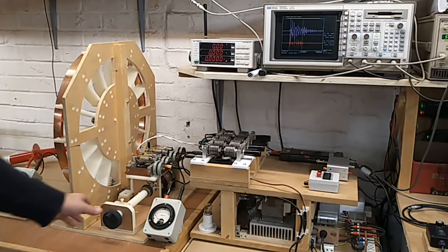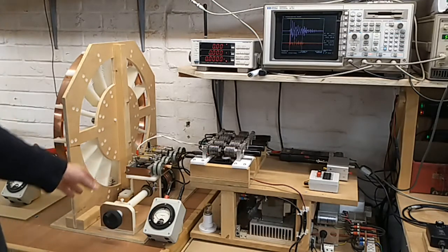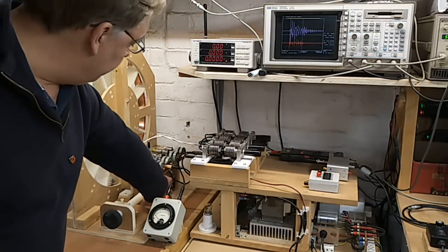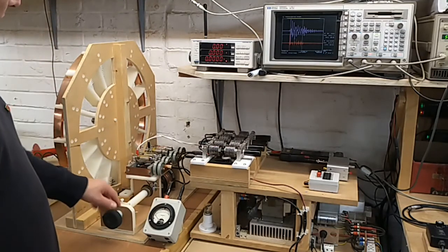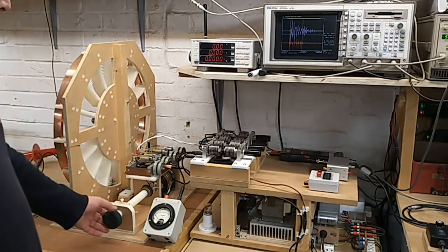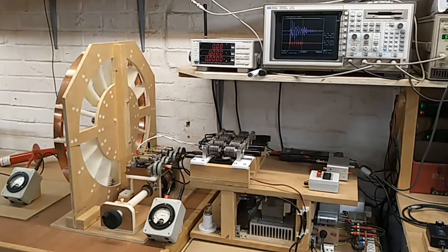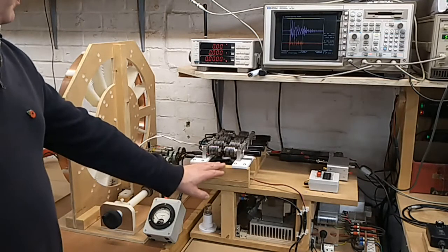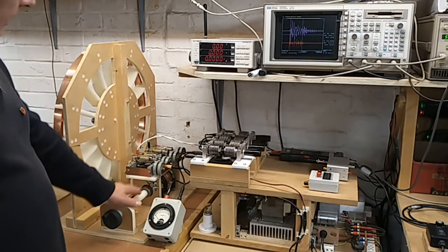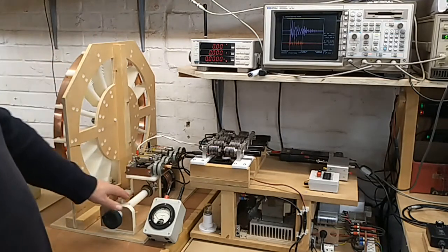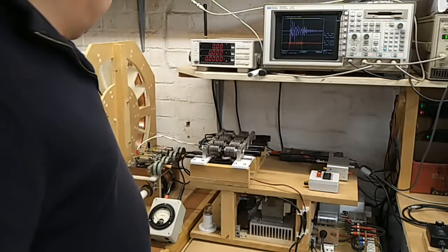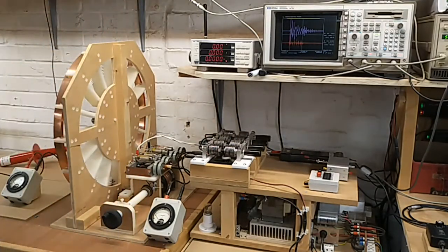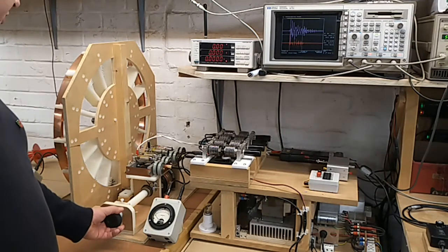Once again, we've got our tuning capacitor in parallel with the primary. This is a 1200 picofarad 4 kilovolt vacuum variable capacitor. We're obviously not running this up full, so that's enough in terms of the breakdown voltage. Ideally, we're running, well, we can see what we're running here. So this will allow us to look at what happens when we tune.